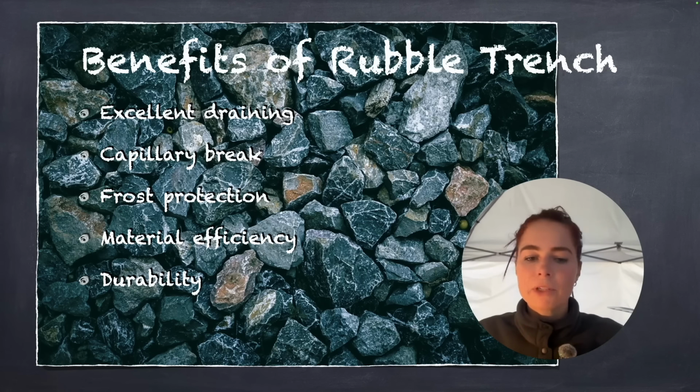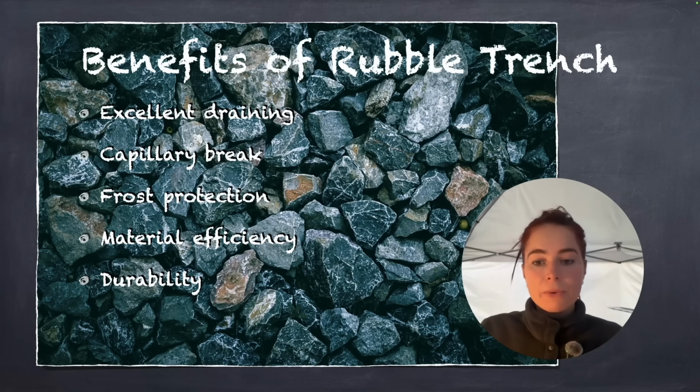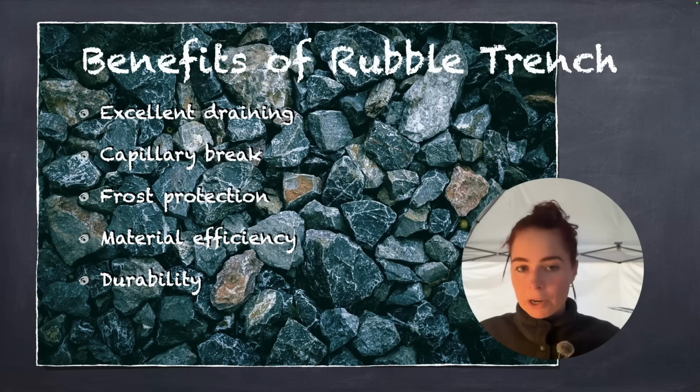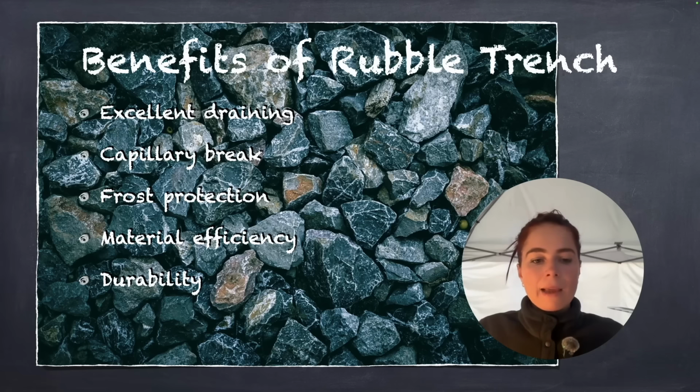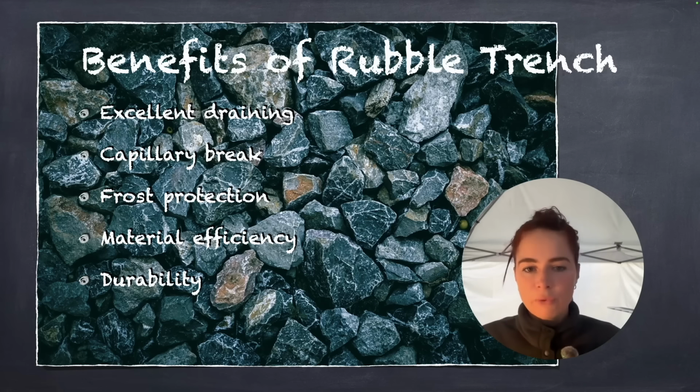And it's not that monolithic concrete mass the way that concrete is. Because that's all one structure, it is prone to cracking. Also, we talked about it's prone to soaking up water because of the tiny pores. But because it's not that big monolithic mass, it can settle a little bit here and there, it can densify a bit, and it can redistribute weight without those brittle failure lines that can happen in concrete.